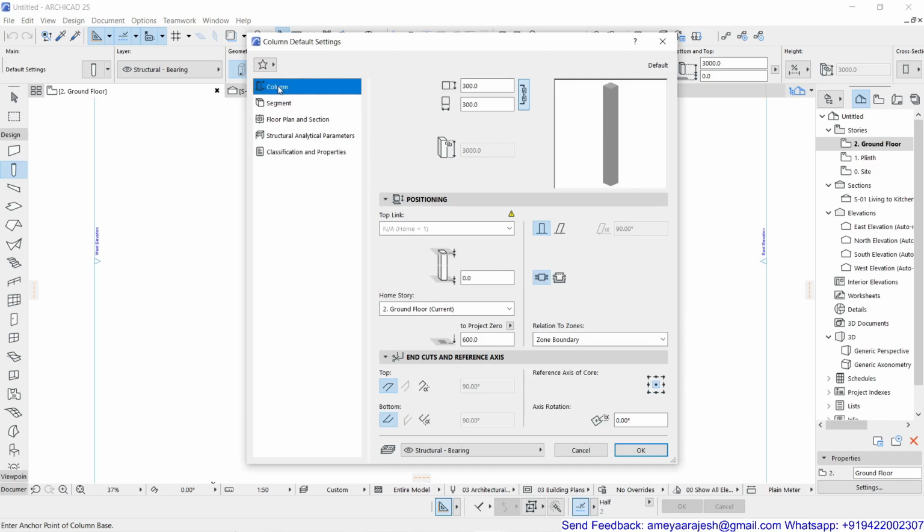And then you can stay back with the first page, column, where you can see there's a cross section height of the column and a cross section width of the column. That is nothing but the length and depth of the column, and the width of the column, which you're talking about. Then there is a link icon. If you want to keep these two values as separate dimensions, you can remove this link. For example, if one side of my column is 230 and on the other side I want to put 450, you can see that now becomes my column profile shape.